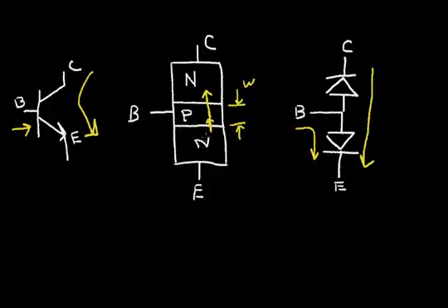So when the diode starts to conduct, an enormous amount of electrons will go into this base region from the emitter side, and they will diffuse over into the collector region. And so for a very small current in this direction, electron flow, we get a large current in this direction.